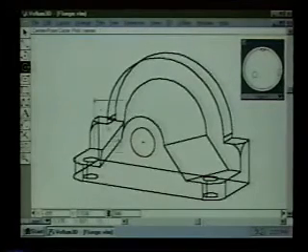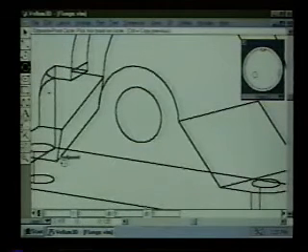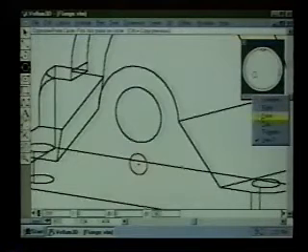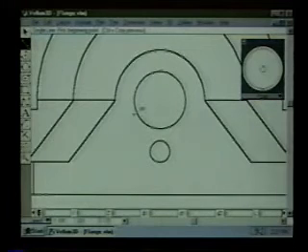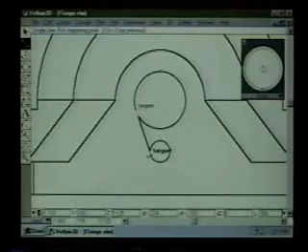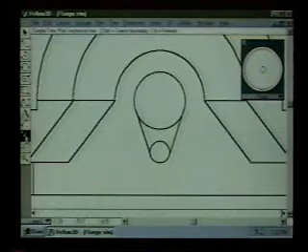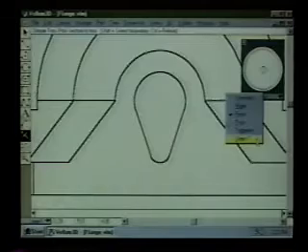Now I'm going to zoom in here as well. Next, I want to draw another circle using a different tool, and I'd like to align the bottom of the circle right off of this point and off of that point, and here's the intersection that I want, and I'll put a circle right there. Now I'm going to change my view to front, and here I can draw a tangent line. So I can get my connected line tool, draw a line from here, press and hold to here, and notice that I see tangent, tangent, and that way I get exactly what I want because I want 2 tangent lines here. And then using these 2 lines on the outside as the boundaries of a trim, I can get rid of this and this. I'll go back to trimetric, or back to view 1.